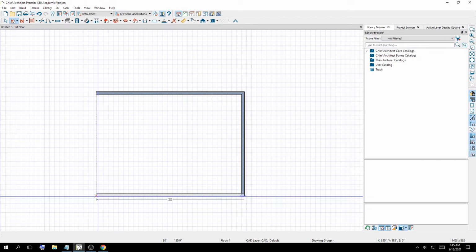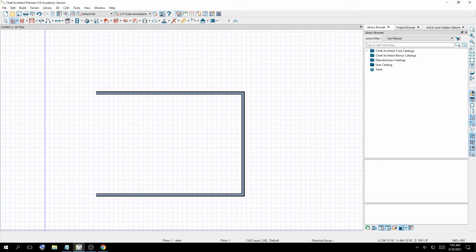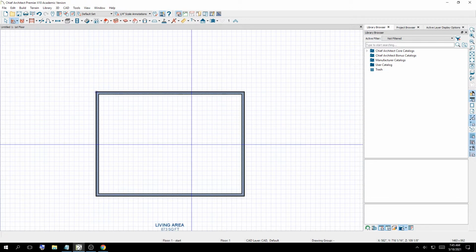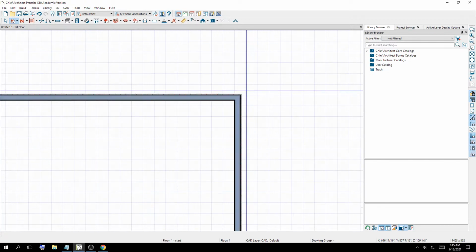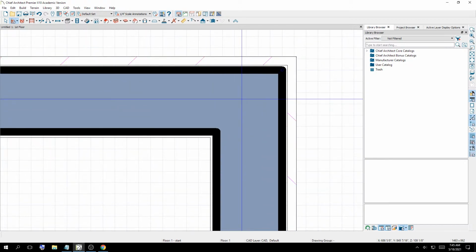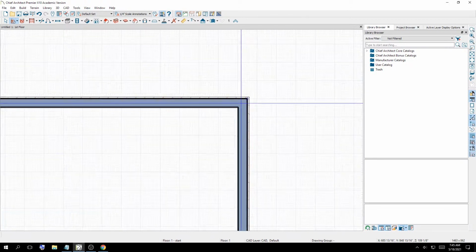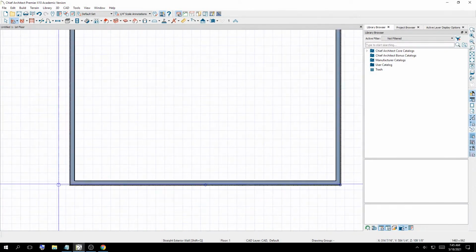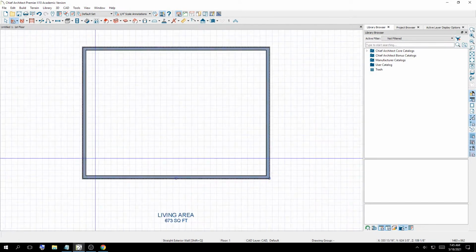Let's drag this over. As you can see, my snap line will show up when I get near it. I'm going to let go of my mouse when I kind of get into the ballpark. And then I'm just going to click and drag up at this point. This is where the cursors really help. As you can see, when you snap, you can see that the corners themselves specifically will heal themselves and become a solid perimeter around the building.